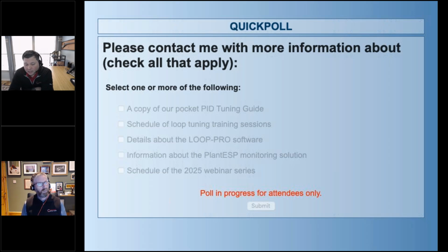That's a good one. My recommendation is to try to do bump tests in a couple of different scenarios. Clearly the worst case, clearly the normal, to determine what the difference in dynamics is. Because if the behavior is significantly different, you may have to employ something like adaptive control that would change the tunings based off of the material you're feeding into the system. You could do a recipe-based tuning approach, and we've done that a lot for consumer products and so forth.